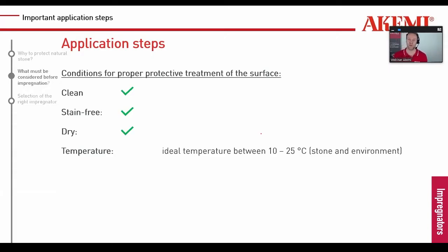This is the ideal temperature, and it's not only the environment temperature, also the stone temperature which you have to be aware of when you are outside, especially in springtime, April, May, maybe. During daytime, you already have a good temperature, like 20, maybe more degrees. But in the nighttime, the temperature can still drop, especially here in Europe, and you can have maybe only 5 degrees in the night. And so your stone is definitely not warm enough, also during the day, to get a good treatment. So here you have to check, we need this 10 degrees minimum to have a good treatment.